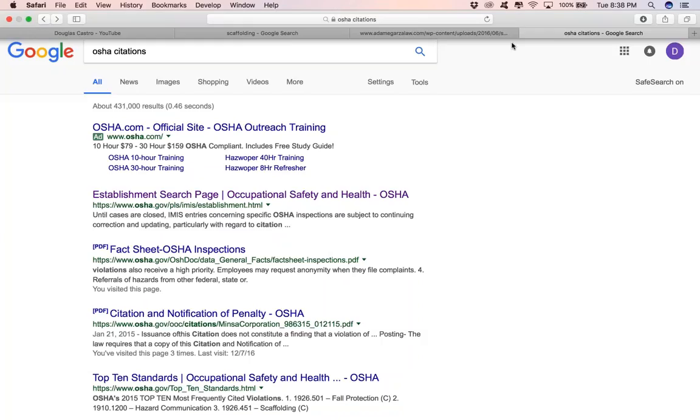And there's a lockout tagout checklist, for example. So what do we want to make sure? That all equipment and machinery is capable of being de-energized. Is it possible to be de-energized? Where the power disconnecting means for equipment does not also disconnect the electrical control circuit, right? Sometimes it'll be electricity, sometimes a different source. Also, are the appropriate electrical enclosures identified? Is it high voltage? How many volts is it? Is it AC? Is it DC?